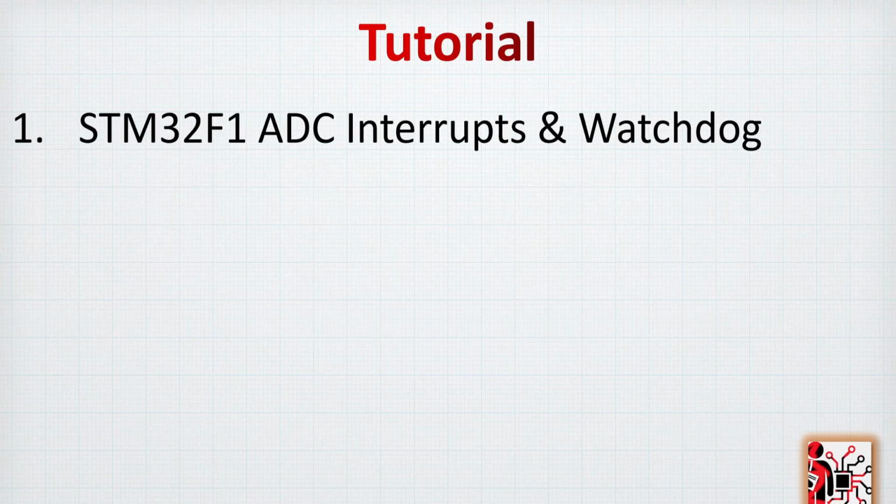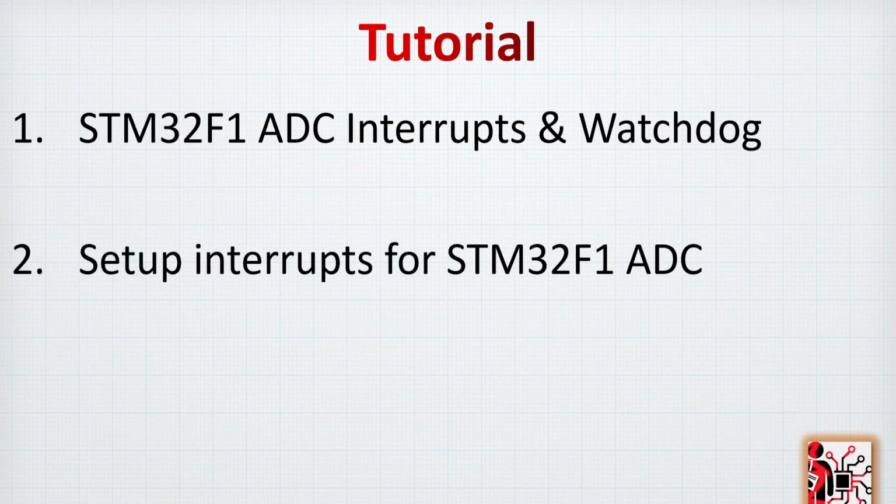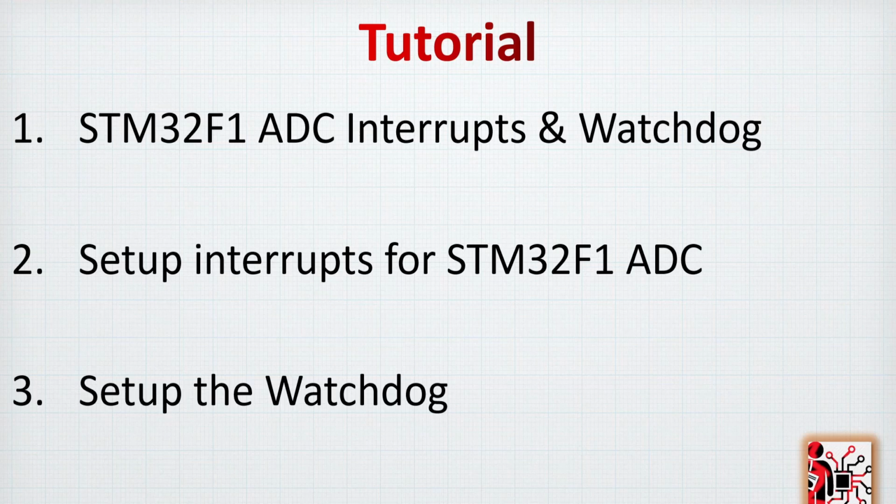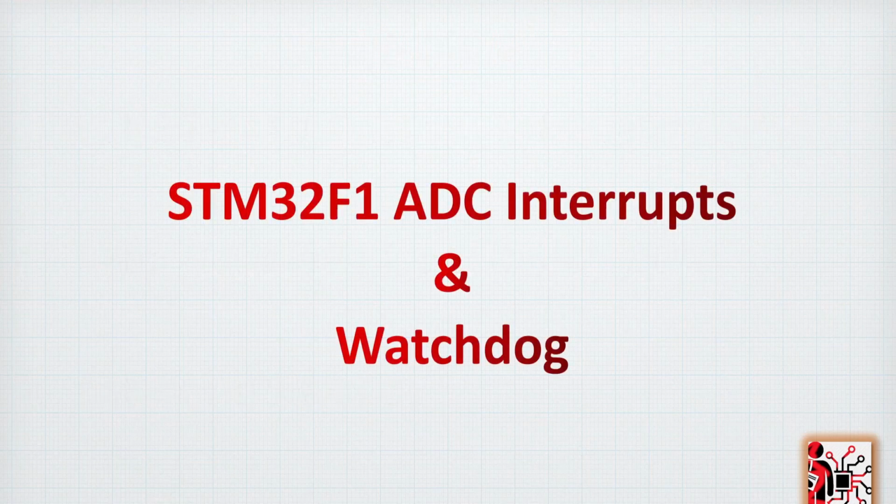Okay, so let's go to the tutorial. It's a very simple tutorial. First of all, let's have a small refresh about the ADC interrupt and watchdog. Then we are going to start coding the interrupt for the STM32F1 ADC. Finally, we will set up the watchdog and have a very simple test to understand how it works. So let's first have a review of the ADC interrupt and watchdog.